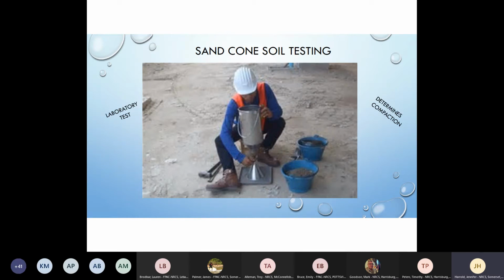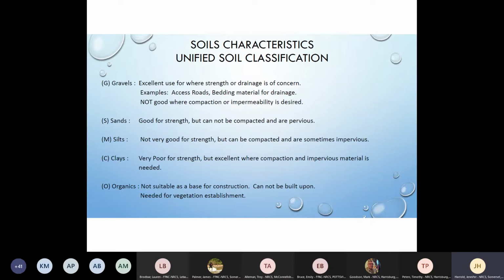For compaction, for some of our projects, there's a certain manure storage that requires making sure that the subbase is meeting the 2,000 pounds per square foot. So they may have a geotechnical engineer come out and evaluate that. But typically we're just using our simple methods. And we always send the work out to a lab if we do need to determine if the soil is suitable or if it could be used for a liner for a pond, the thickness and everything.